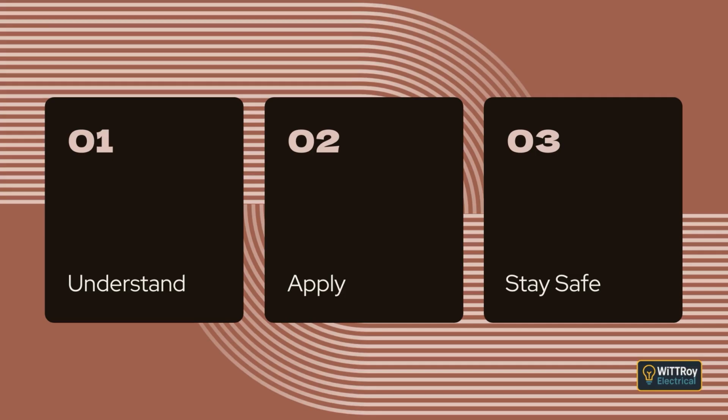Clause 3.6.1, General. Under normal service conditions, the voltage at the terminals of any equipment must not fall below the minimum value specified by the relevant equipment standard. If the equipment does not have its own standard, then the voltage must remain high enough that the equipment can operate safely and properly. Clause 3.6.2, Value.